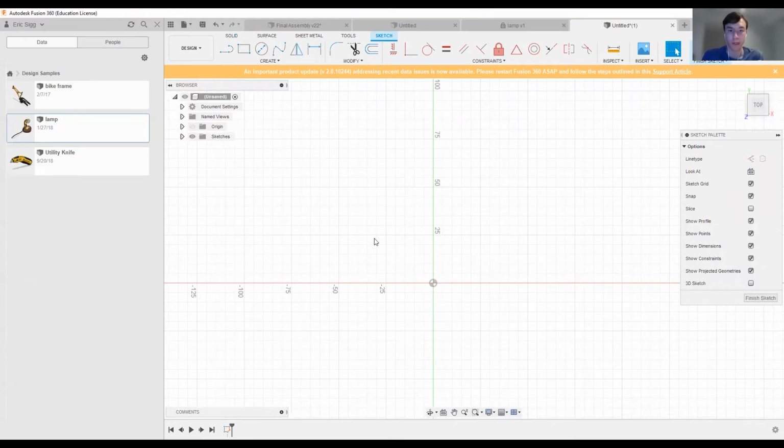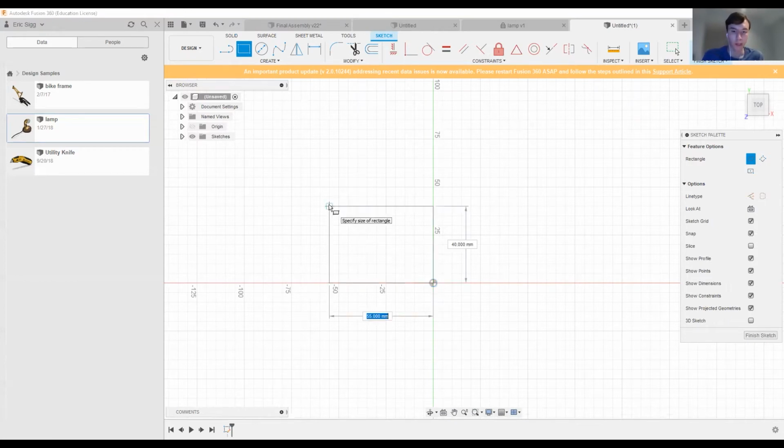From this point I can draw a rectangle on the ground, or a square, I guess. So I'm going to click on the 2-point rectangle tool, which I've already done. And you can see now I have this rectangle that I can drag around. It has these 2 units. In order to create a perfect cube, I'm going to say I want a 10-centimeter cube.